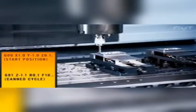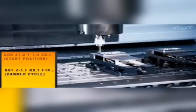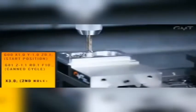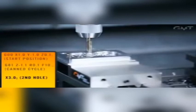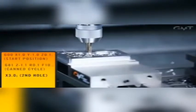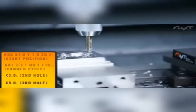Programming a CNC machine to drill holes is simplified with the use of canned cycles. The table and spindle initially traverse to the starting position of the first hole. The G81 command, followed by various parameters, initiates the canned cycle. G81 is a modal command, meaning it stays active until another command cancels it. Drilling additional holes only requires specifying new coordinates.